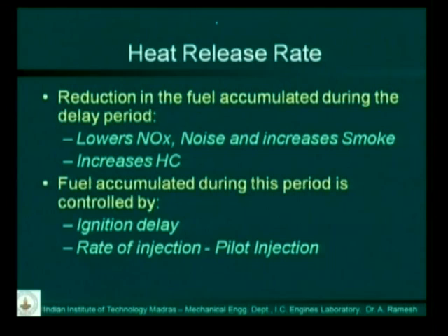So now we will go back to the heat release, and we saw that reduction in the accumulated fuel during the delay period lowers NOx, lowers noise, but it will raise the smoke because diffusion will go up. Fuel accumulated during this period is controlled by the ignition delay. It can also be controlled by pilot injection, which is what we saw now.